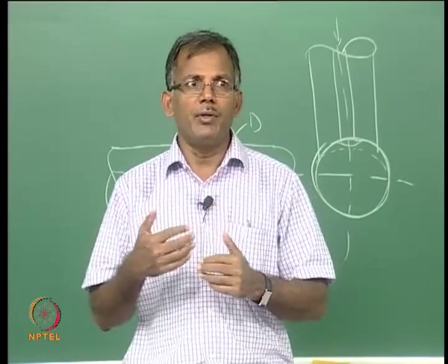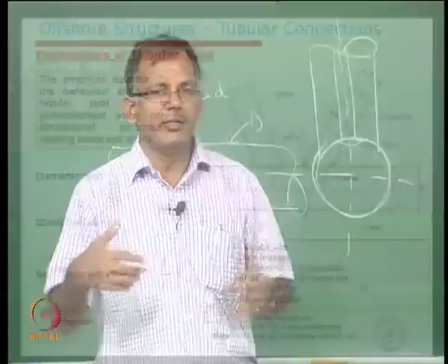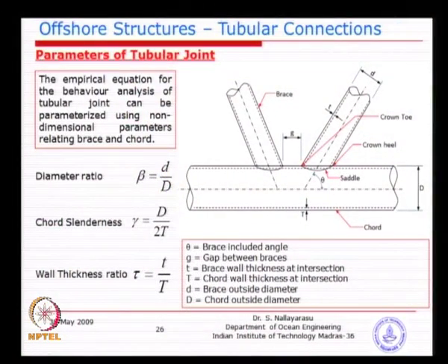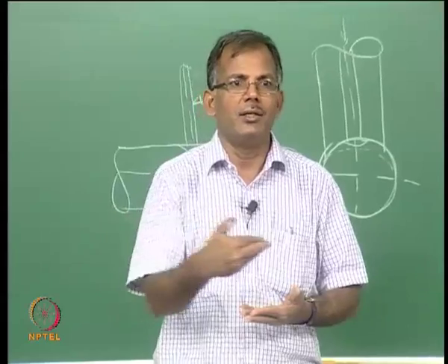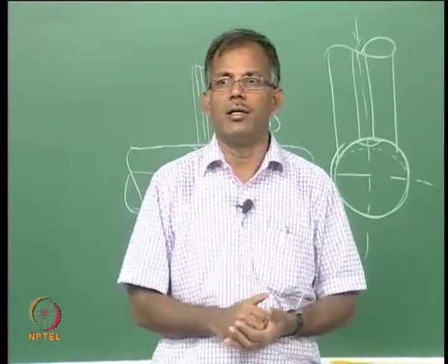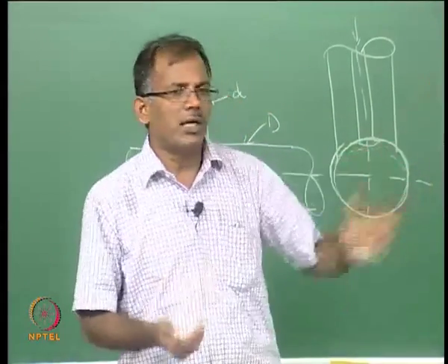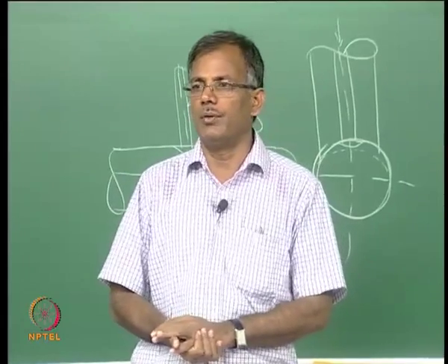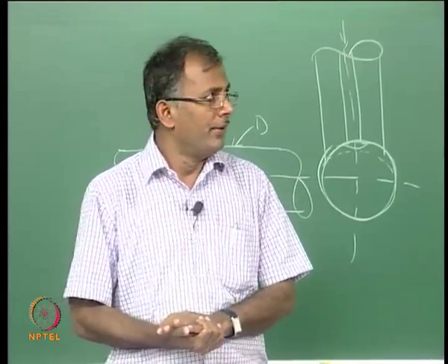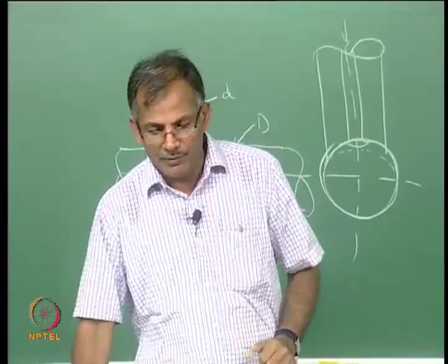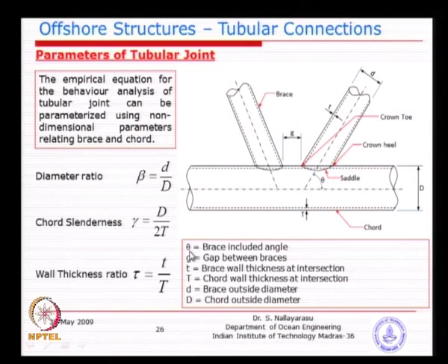So, what happened to the remainder of the load? When you have a 45 degree, some load goes normal to the chord, some load goes as an axial or inline force to the chord. Inline force, I think it's not a problem, it can take a large amount of load because big diameter is there. So, the angle is definitely going to affect the capacity because the amount of normal component that goes to the pipe is going to be reduced.